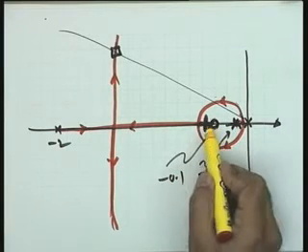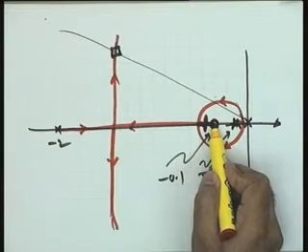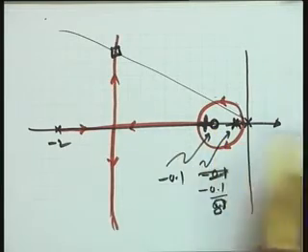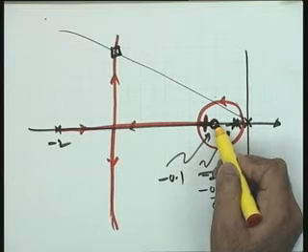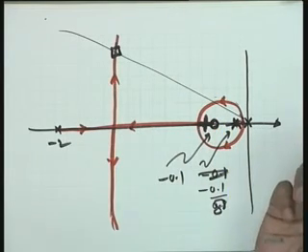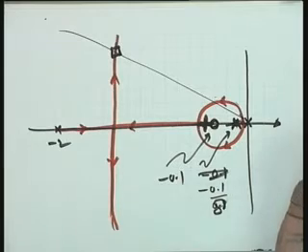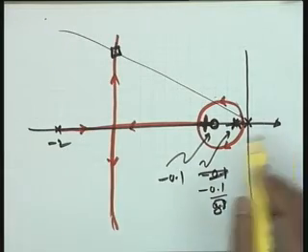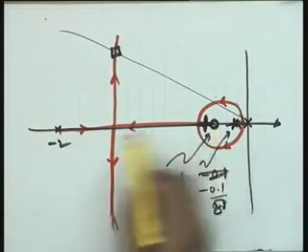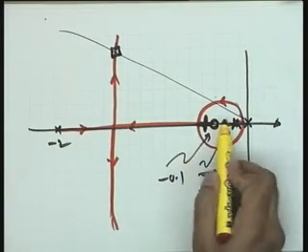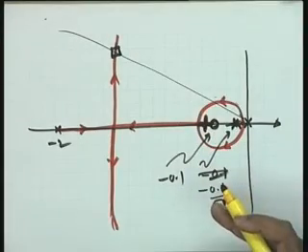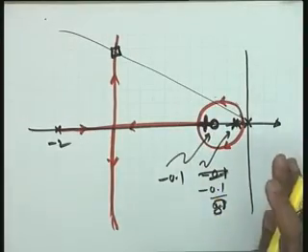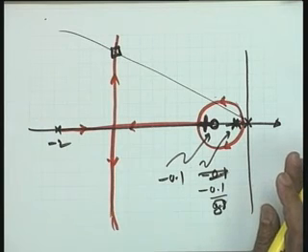If it is not satisfied, if this is not sufficiently close to this particular 0, you can make an adjustment of the pole 0 locations so that the third pole is sufficiently close to this particular 0, and this pole 0 adjustments naturally you are going to do using the CAD software, not by the paper and pencil design. This is only the method, the guidelines given to you. The third pole will lie somewhere over here. So by suitable adjustments here and there, your dominance condition is more or less satisfied, and finally it will turn out with the help of simulation as to whether your requirements on the transient and steady state requirements are satisfied or not.